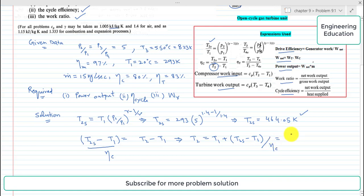Putting the values, T1 is 293 plus T2S is 464.05 minus T1 293, divided by isentropic efficiency of the compressor, 0.8. Simplifying this, the value of T2 comes out 506.8 Kelvin.